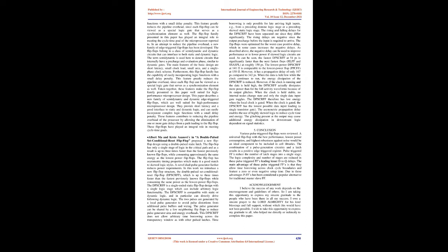Fabian Klass, Chaim Amir, Ashutosh Das, Kathirgamar Aingaran, Cindy Truong, Richard Wang, Anup Mehta, Ray Heald, and Gin Yee, in A New Family of Semi-Dynamic and Dynamic Flip-Flops with Embedded Logic for High-Performance Processors, presented this paper. In an attempt to reduce the pipeline overhead, a new family of edge-triggered flip-flops has been developed. The flip-flops belong to a class of semi-dynamic and dynamic circuits that can interface to both static and dynamic circuits. The main features of the basic design are short latency, small clock load, small area, and a single-phase clock scheme.